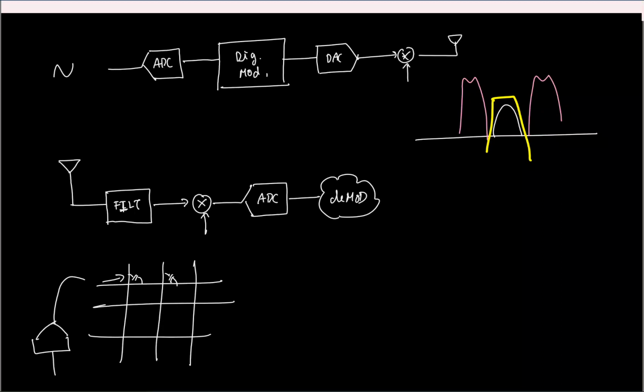So again, the point is, if you take your phone, it houses a whole lot of ADCs, and the specs are all broadly different, right? For example, the specs for a touchscreen ADC, they'll have a very high resolution, but the bandwidth will be very small. Now, if you come to a radio receiver, it will have a medium resolution but relatively high speeds. And when you come to your serial links like USB or LAN, it will be ultra high speeds but really low resolution. Okay. And not just mobile phones, right?